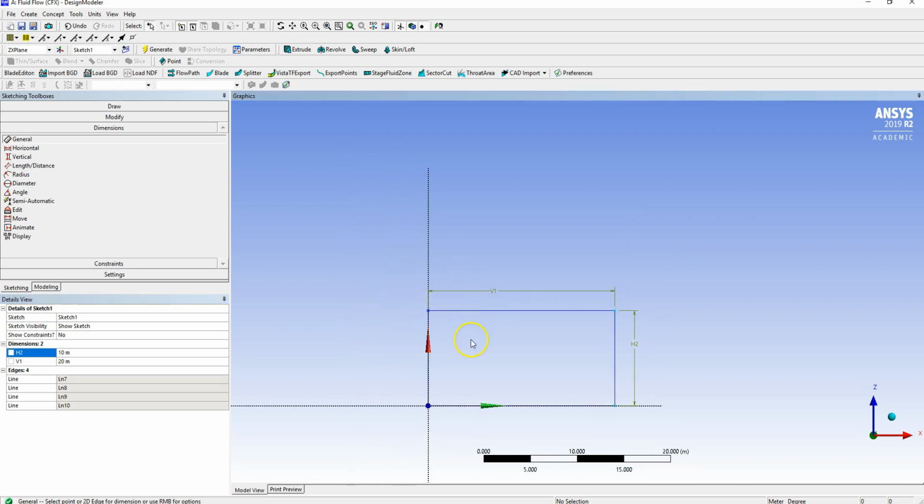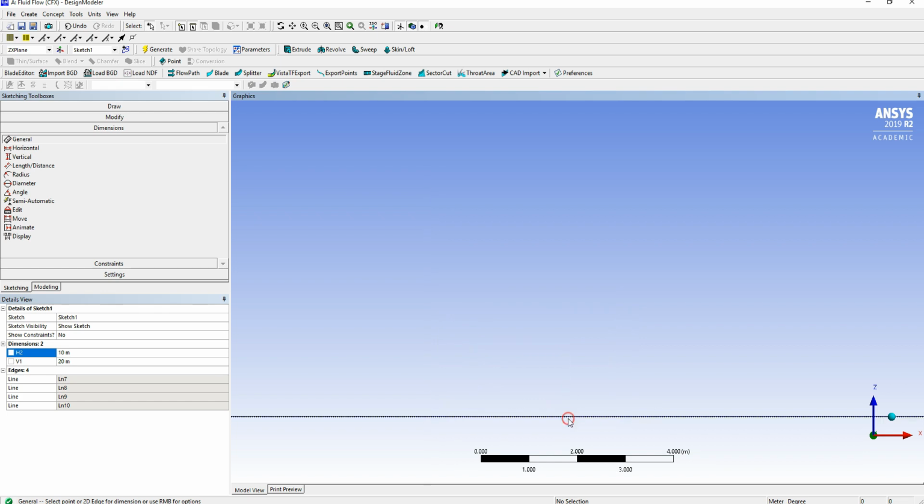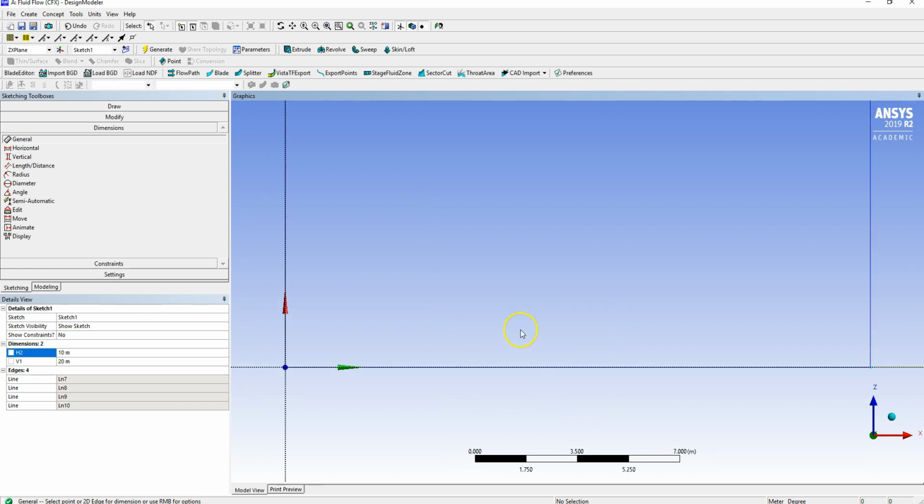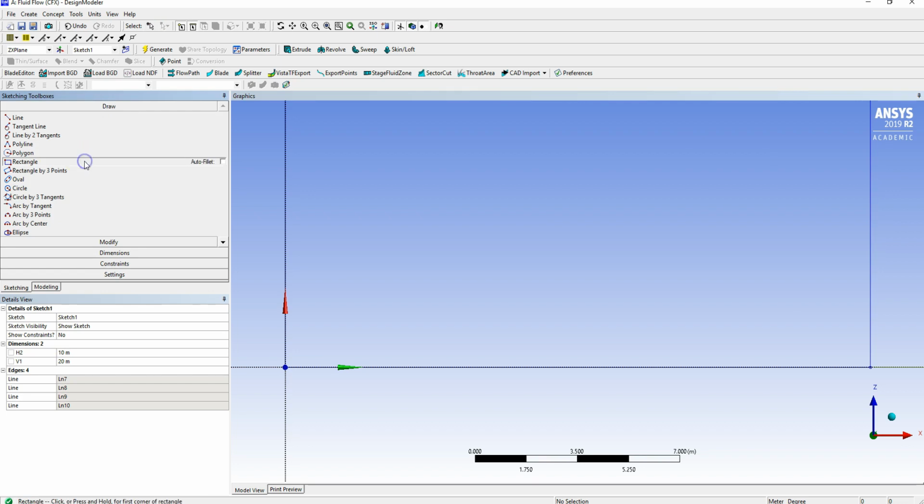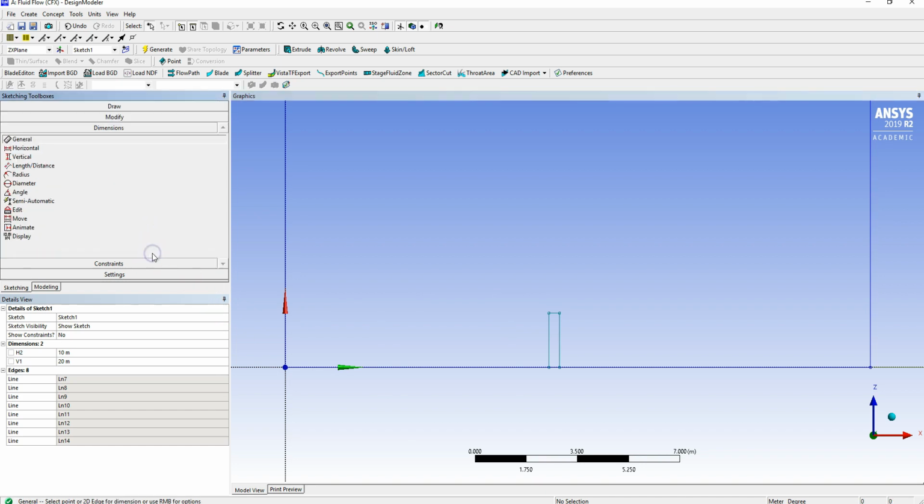And the next thing we need to do is create the shelter that's going to sit somewhere in the middle here. So the shelter is a relatively simple construction. Just going to use another rectangle that's coincident with this axis to create the back wall. I'm going to leave it thicker than it needs to be, just so it's easy to select that line in a moment. And I'm going to say that it's 2.5 meters tall and 3 centimeters deep.